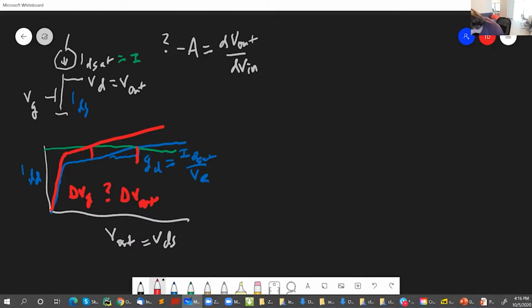And so you can see here that it crosses where the currents are the same. They must be the same, right? It crosses at a much different voltage. And the flatter this curve is, you can see the more the voltage is going to change when you change the gate voltage. And so the way you model this is you use what we had before. You just model the transistor circuit as a combination of an ideal current source, which is the saturation current, which is ID sat, the bottom transistor. This is the load up here. And then in parallel with that is the drain conductance, GD.